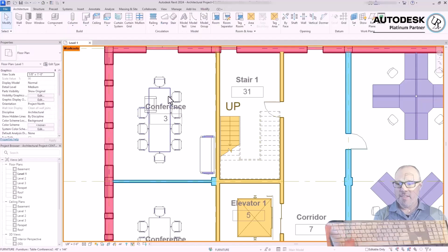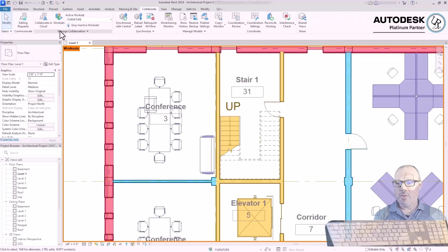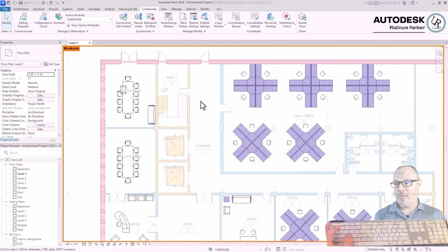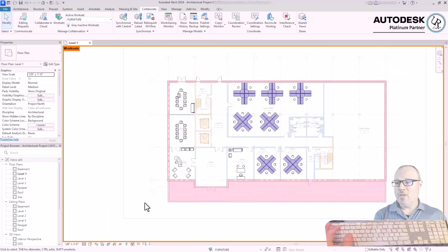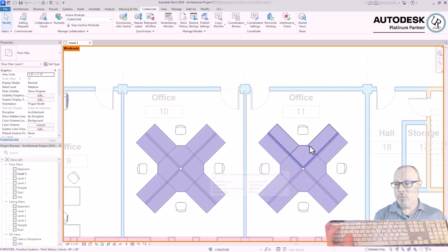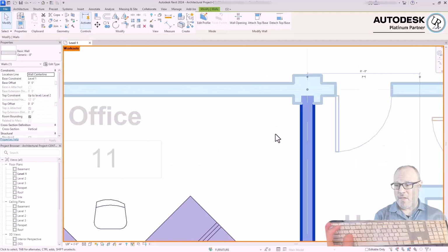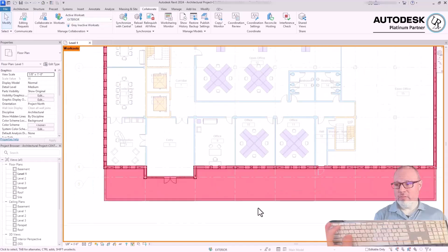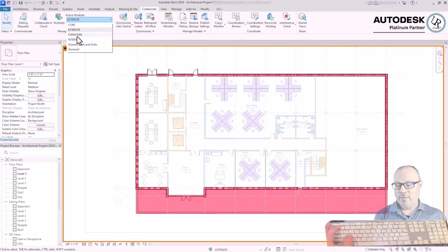In the Collaborate tab, Manage Collaboration panel, next to worksets you have gray inactive worksets. Selecting that will disable all of the other worksets from being vibrantly colored in a dark graphic, and it will gray everything else so it looks less intense, indicating that you're on a different workset than the others that are selectable. You can still manipulate content, but they are grayed out because you're not on that active workset. When you switch to different worksets, it will highlight that information with a darker color.